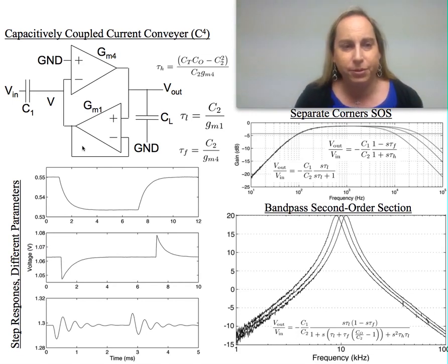But the typical circuit as it's used today, you might imagine two OTAs, particularly if this is done in an FPAA structure. It has a very interesting thing for a gm-C filter because it's one of the few, and as far as I know the first, that used a capacitor as the input for a bandpass. It's nice because it's a capacitive input with two OTAs, so it actually tends to be lower noise than other topologies, because the capacitance itself is not an issue.